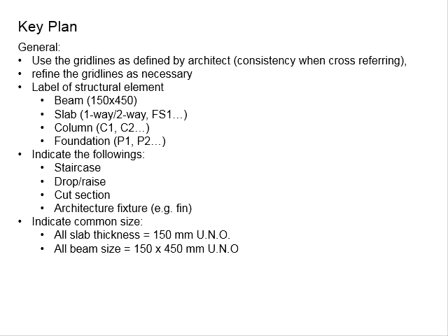There is a high concentration of information in the structural key plan, and it's going to be the reference point for all the other technical drawings produced by the engineers. You need to provide sufficient details and information regarding each structural element, their layouts, their design, their reference numbers, etc. Other than that, there is also some important information to be incorporated there and made known to the contractor, to minimize their effort flipping through the structural key plan and the floor plan of the architect.